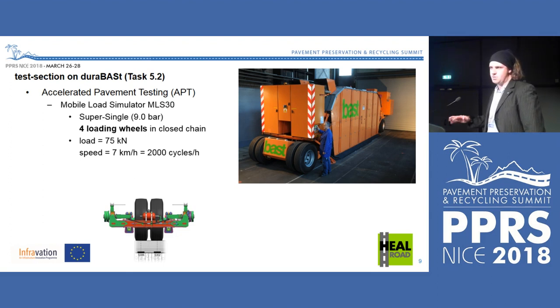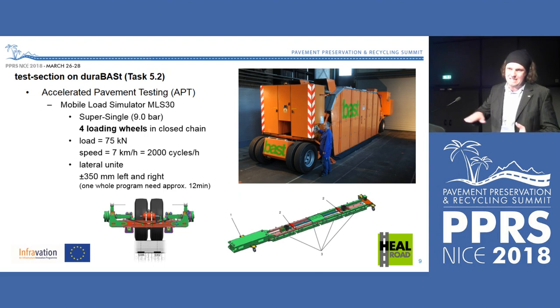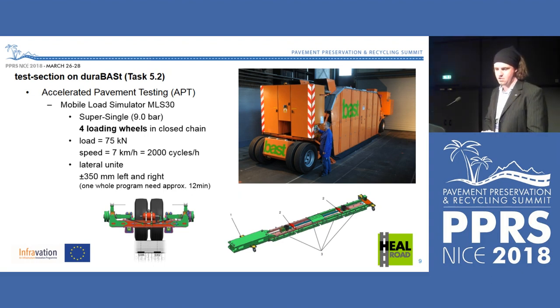That's approximately walking speed. That means we have a lot of pressure for a long time when the tire is on the surface, and additionally, we had a sideways movement, where the machine was moving 350 millimeters left and right. So the speed was very low, and we could introduce shear forces into the surface layer. The lateral movement happens during the loading process, so we don't have to lift up the machine and put it sideways. It's going sideways at 4 millimeters per second.